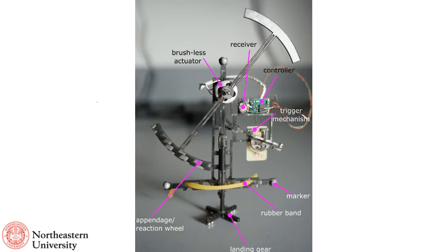The platform that we developed and used in our study is called Harpoon. The overall design allows a limited self-sustained sensing, actuation, computation, and communication between this robot and a master computer that is responsible for costly off-board computations. An actuator adjusts the angular velocity of a bob with respect to the body to create differential inertial forces.